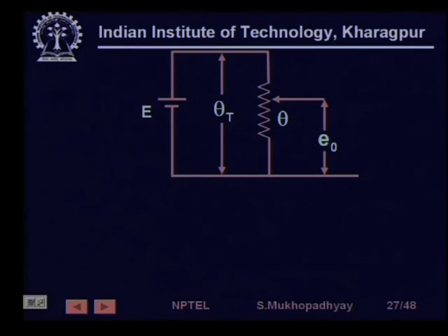For example, typically, a potentiometer. I was talking about a resistance, and a potentiometer is nothing but a resistance. Potentiometers typically measure position, so the potentiometer will be connected to this variable point. As the variable point moves, the voltage that you will get will be directly proportional to the position. Since the position is actually a mechanical variable, there is not going to be too fast a movement.